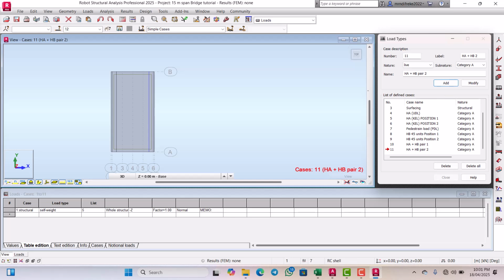So the next thing we will do is for us to define each of these loads. So we are going to start with the superimposed dead load. Now for the structural dead load, the structural set weight is an inbuilt load that we have in the software. So we don't need to calculate the set weight.